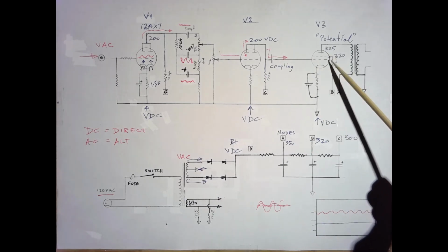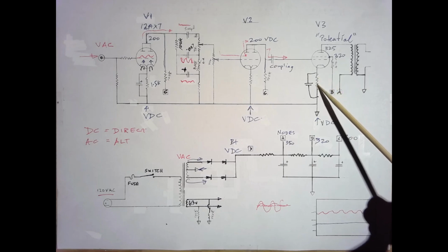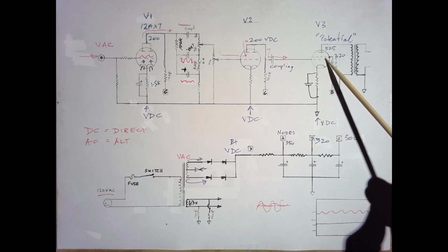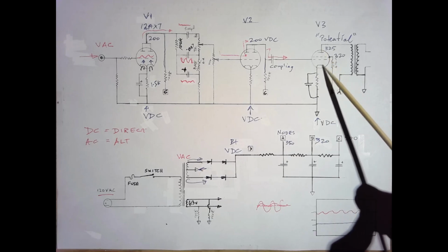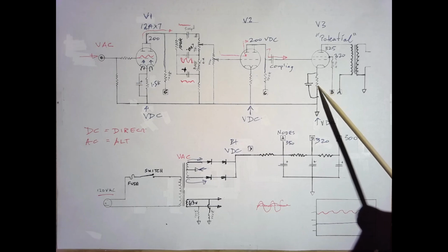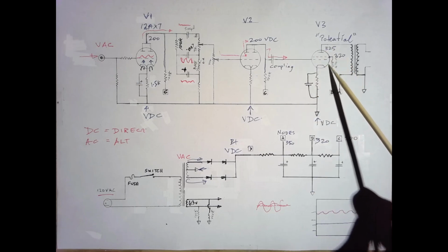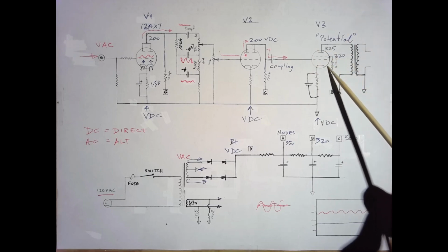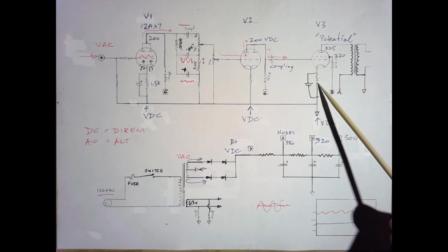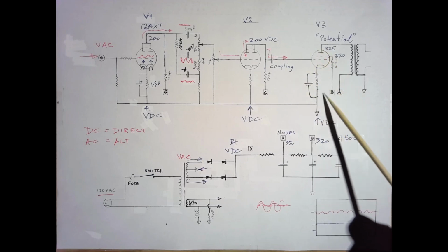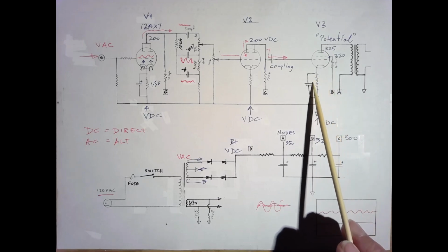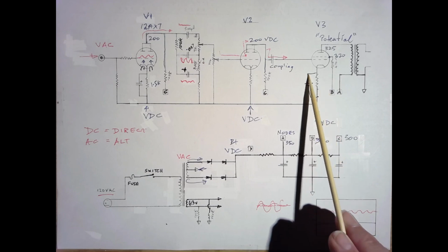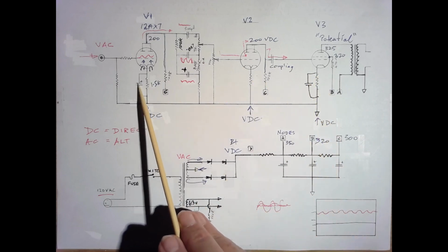And when we bias the power tube, the size of this is very important because, again, it either clamps down and controls this tube very powerfully and limits what it can do, or you put a smaller one in and a smaller resistor, and you'll get all sorts of things going on. And in fact, if it's too small, there's a high voltage here, we've got a big signal coming through, and it can run away and overheat and burn out, and this is where you have red plating. And that's usually in this kind of design, which is called a cathode resistor bias. Then we choose the size of this resistor very carefully, and the bypass capacitor acts in exactly the same way as it did in the preamp stage.